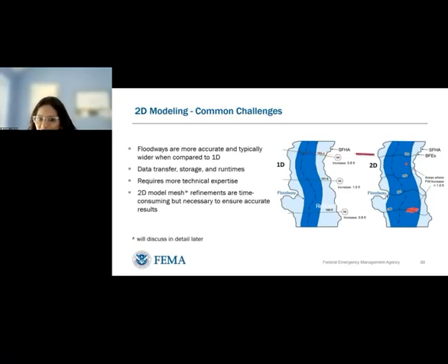The main reason is that the floodways are analyzed based on time, like we talked about before, and account for all the water that accumulates in that location. So even if the water is traveling from a different location, coming slowly, it accumulates in this location. So typically there's going to be much more volume of water. That's why typically the 2D floodways are a little bit wider.